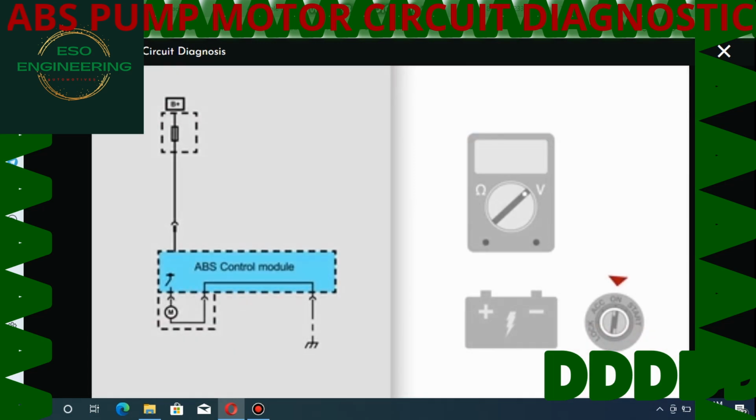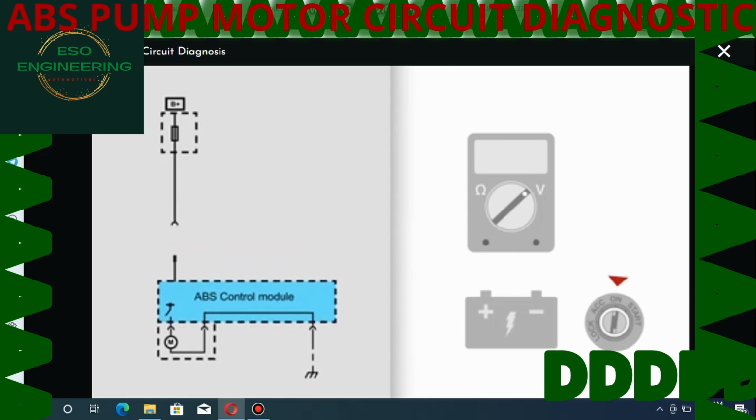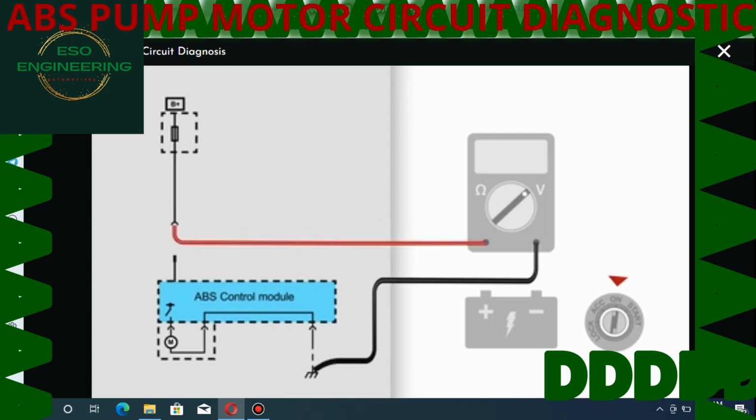To test for resistance in the circuit, disconnect the ABS harness connector. Connect the meter between ground and the supply terminal at the ABS harness connector. If a reading of less than battery voltage is present, this will indicate excessive resistance in the circuit. To isolate the fault, continue to test each connection working back towards the fuse.